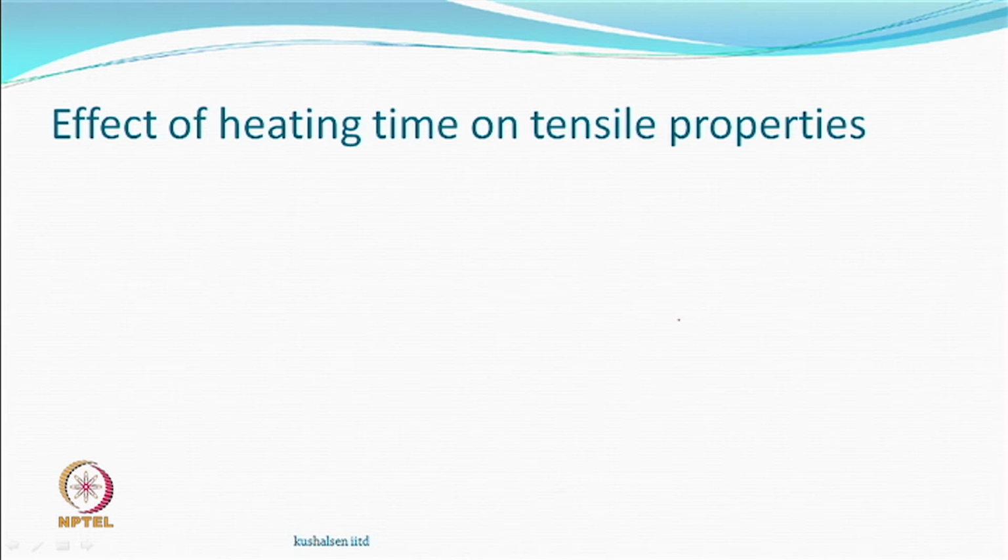So, what will be the effect of heating time on tensile property like tenacity? Remember, because we are setting a twisted yarn, the orientation of the yarn is going to go down. So, when you test any of these properties, it will only go down. Now, the question that remains is, is it so important that you should worry? Well, it depends what you are doing with it.